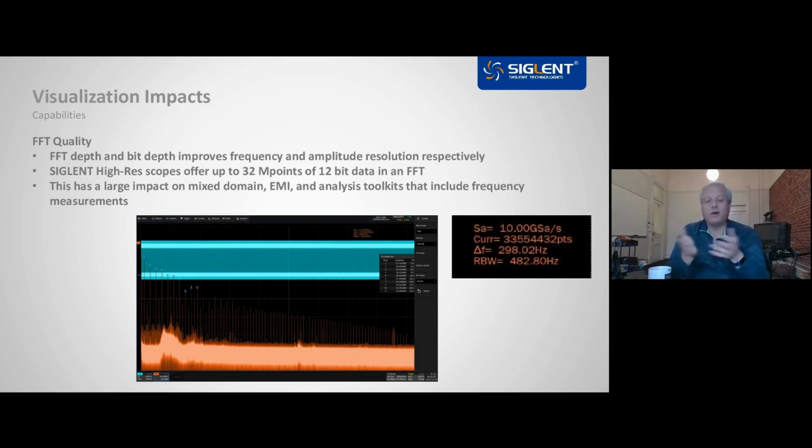So we combine this with markers, peak readings, and scaling tools to capture signals equivalent to a wideband real-time spectrum analysis look you can correlate now with your other time domain signals. As you might expect, the isolation we talked about before is critical in these applications, since the RF signals are especially good at creating noise on adjacent channels.